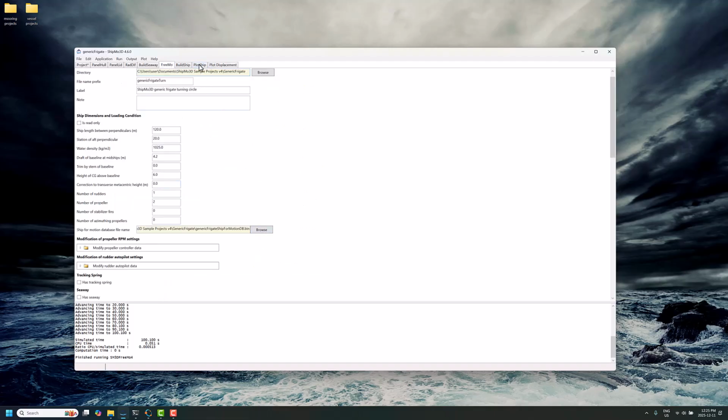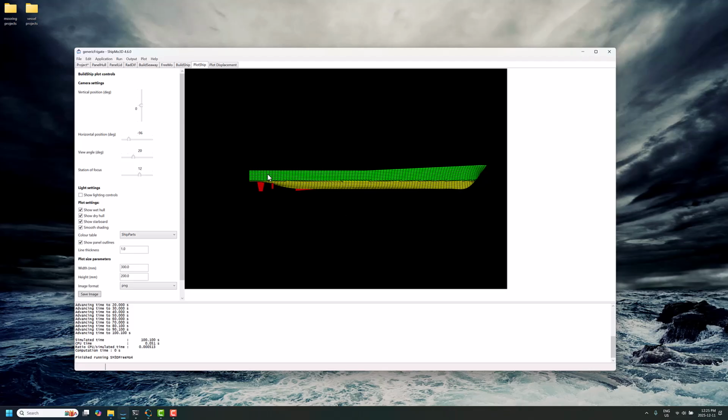But anyway, the idea here is that going through this calculation process is very rapid, and you can do these sensitivity studies, getting a really robust idea of what your ship turning performance is. In early stage design, you can do this way ahead of doing any CFD and certainly any kind of tank testing, and really get a confident idea of what kind of appendage size you would want to use.